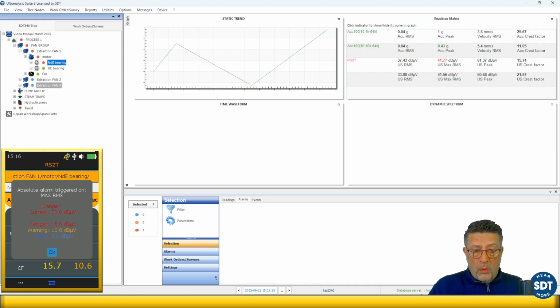This can be quite useful information, because if I am in an alert level and my warning is at 10 and my measurement is 9.9, it's quite important to be able to see it, to understand that yes, you are officially in alert, but you are basically 0.1 away from warning, so you can have a better feeling about that, especially if the gap between three levels of alarm is high.